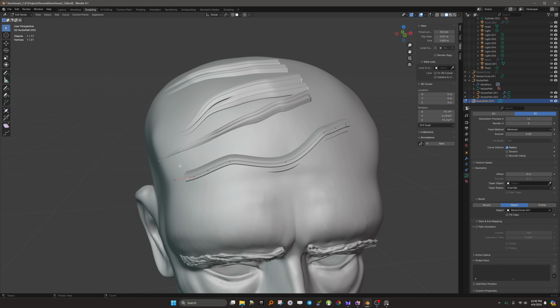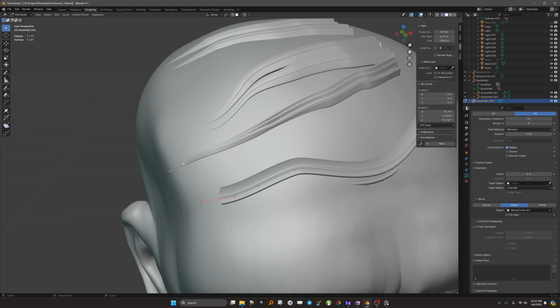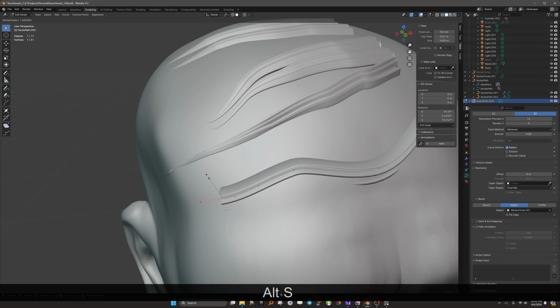All right, so what I'm going to do first is scale this end down to nothing. So the way you do that is you press not Alt R, Alt S, and 0. Just like anything else in Blender, if you are transforming and you know precisely how you want to transform it, whether you're translating it in space, rotating it, scaling it, or whatever, and along which axis, you can press the activation key, which is, in this case, scale. And we don't have to do an axis because there really aren't any axes along this curve. So we press Alt S, sorry, and that puts us in scale mode.